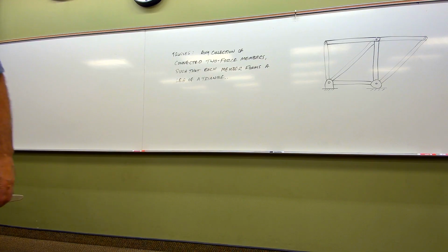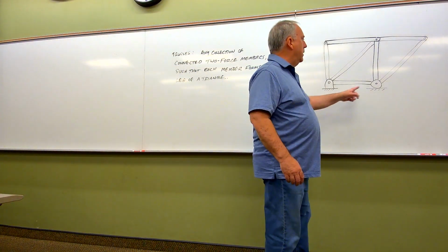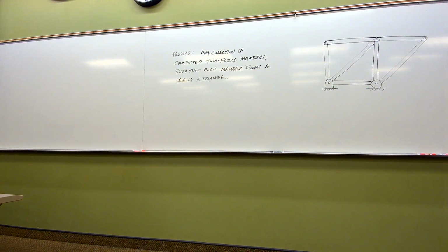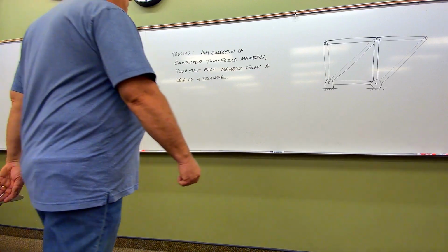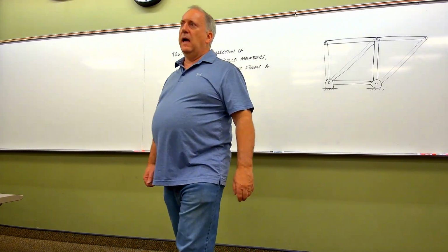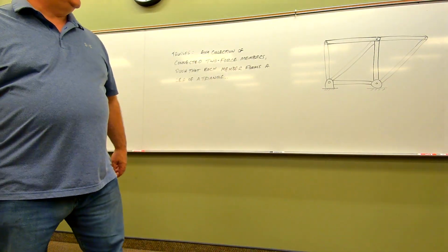Think about it. If I had a pin connection here and a pin connection here, 2 pins, I would have a grand total of 4 unknown forces. I don't have enough equations to solve that. Does it mean it can't be done? No, it means we got to get pretty creative in how we do it. There are ways to do it, but why bother? We don't need to do that. Let's just make these nice, simple connections like that, and then we can analyze it and move on from there.